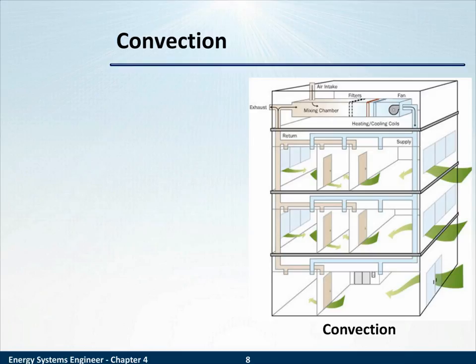But in addition, shown here is convective transfer between interior spaces. Of course, if you have interior spaces that are conditioned to different set points, that transfer can cause those two air conditioning systems to battle each other. These are both, whether from outside in, inside out, and between interior spaces, both are convective heat transfer.